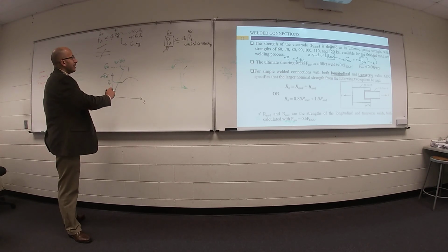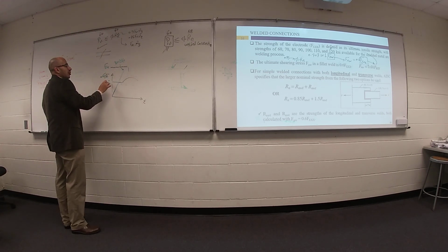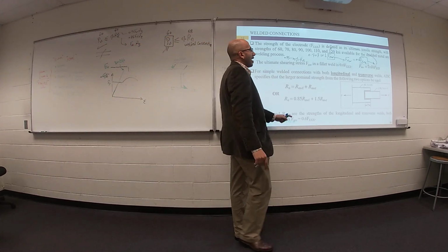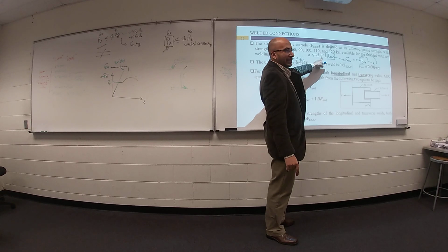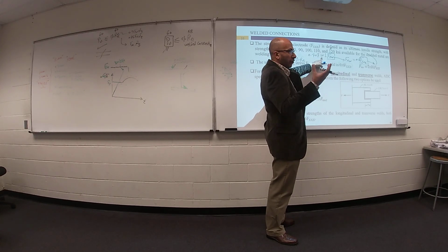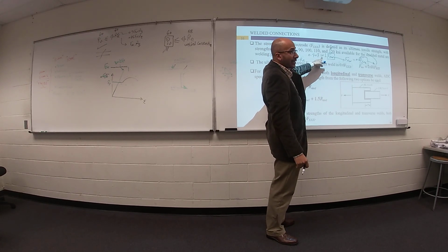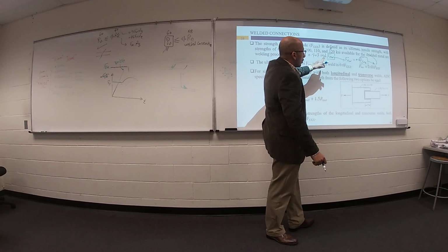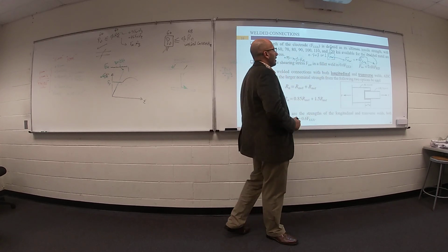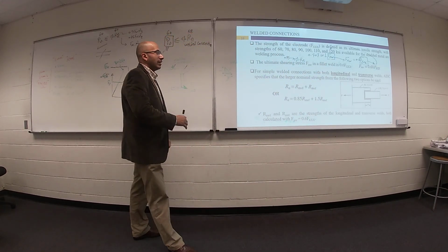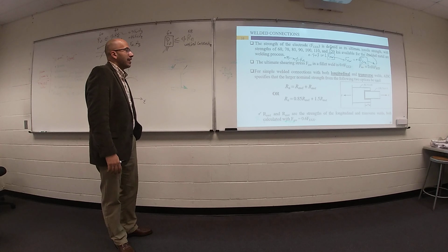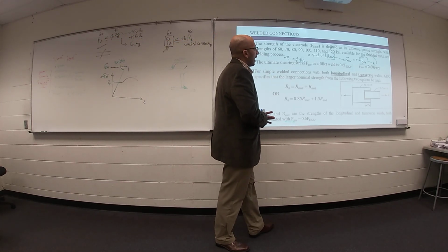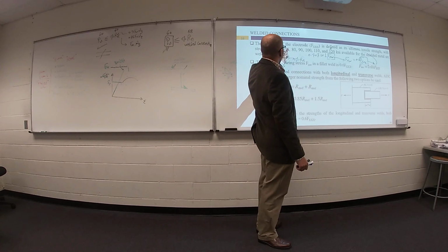Okay? You said the material is stronger, but the material is not the only factor. We have other factors, like size of weld. Maybe you have very strong material to make the weld, but you have very small size. Maybe you have a very small length of weld. So not only the material will control the design. Anyway, so for a welding connection, first I need to figure out what is the type of electrode